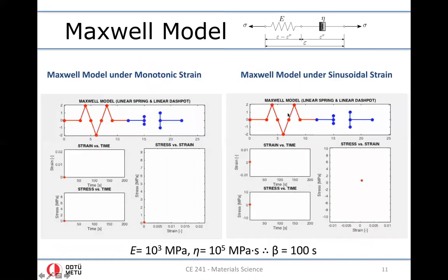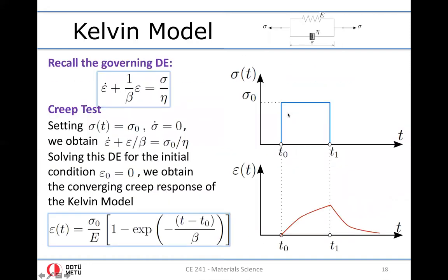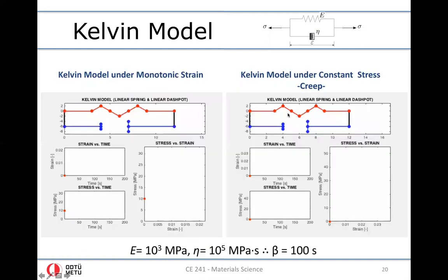Therefore, when you have rate of the strain infinity, in the Kelvin model, the amount of stress that you need to apply to generate such a constant strain, epsilon 0, is infinity as well. You can do it practically by applying a very high stress to generate constant strain, but it is not exactly what we theoretically see here. So you, in the first place, always apply strain at a finite value. And the higher the rate of the strain, the higher the initial stress will become, of course.